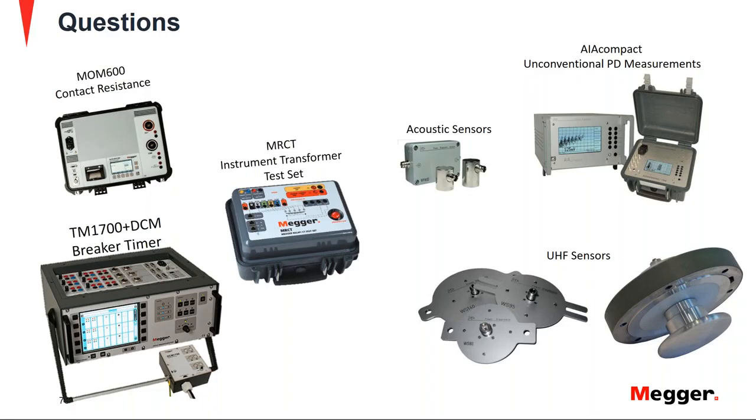All right, thanks, Charles. To Volney, can DCM be used for other circuit breaker applications? Absolutely. The very first reason that DCM was developed was to test regular air insulated breakers, or breakers in air insulated substations with both sides grounded, and this was developed to improve the safety, to avoid removing the grounds once the breaker was grounded, for all of the maneuvers and the procedures to be able to test it. So that was the initial application of the DCM development from Megger 20 years ago.